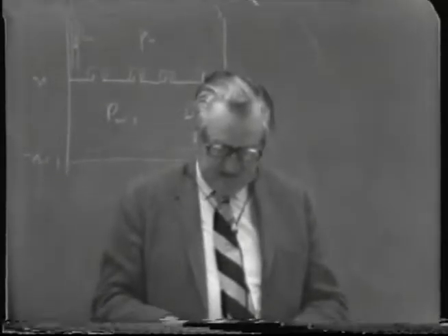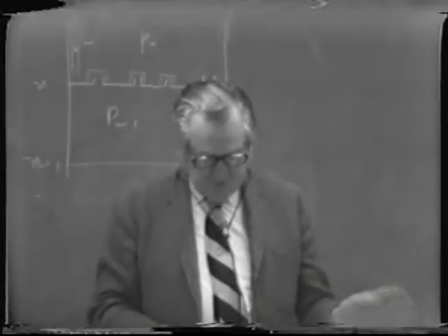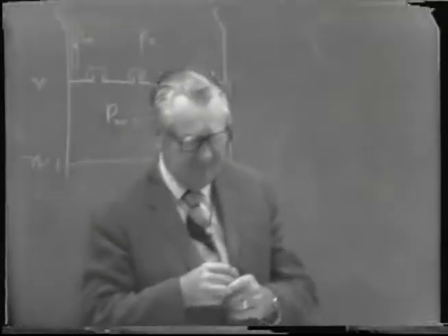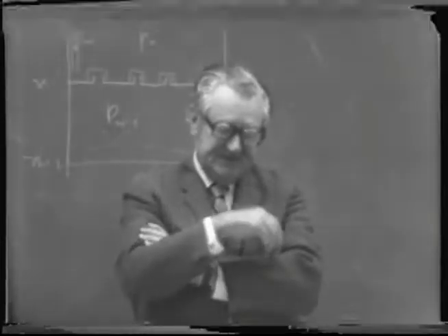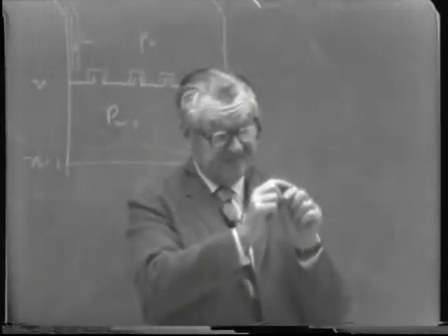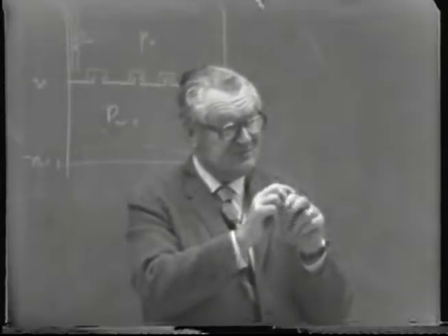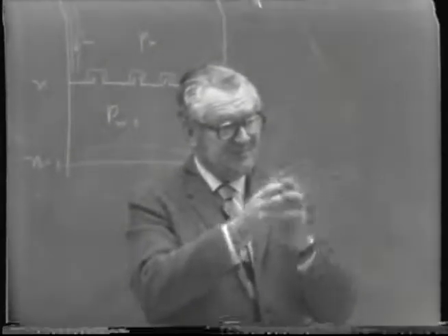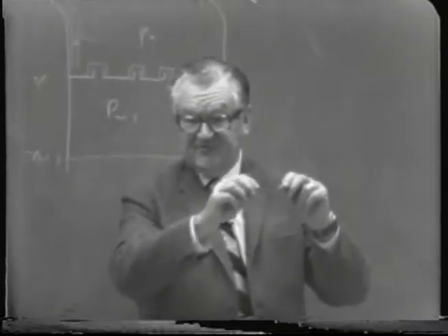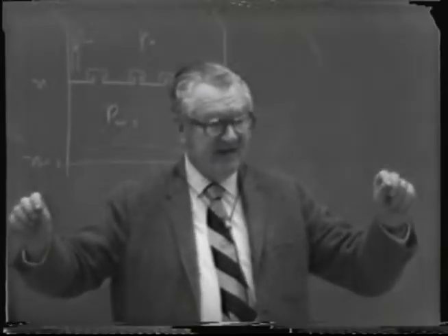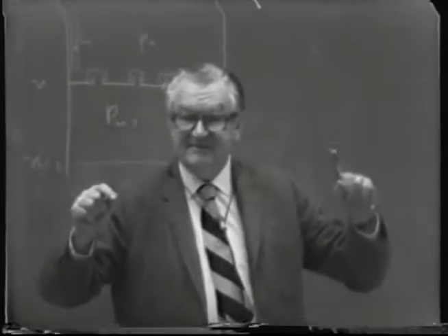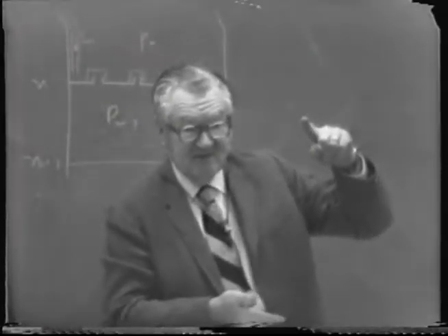But nevertheless, one of the problems with handling all the pumice was that some of the solids didn't disintegrate very well, and particularly the fibers of residual stems would simply separate like fibers of cotton, and tend to form strands that would hang up on sharp edges, such as the downcomers and the seal cups at the bottom of the downcomers.